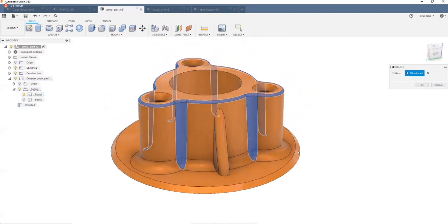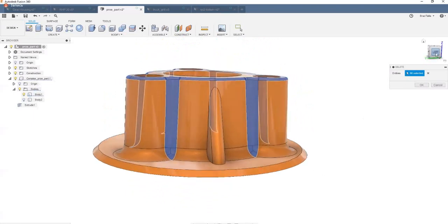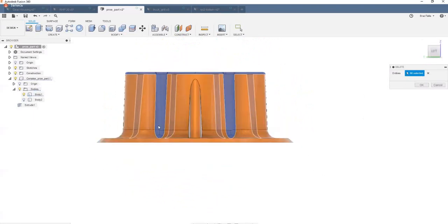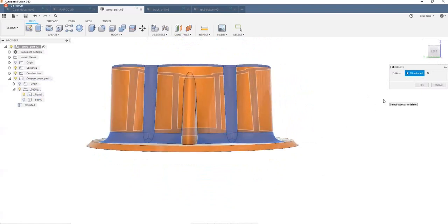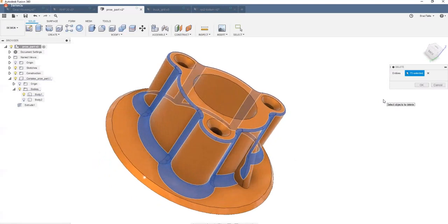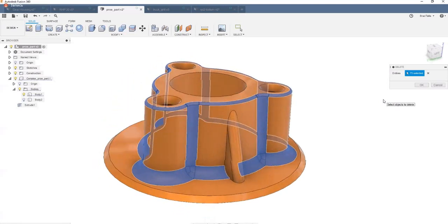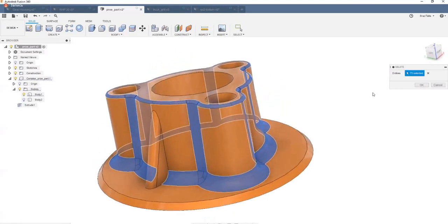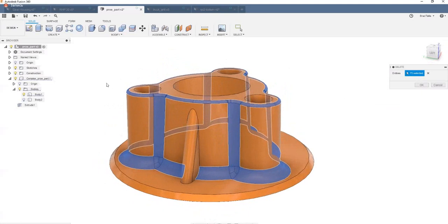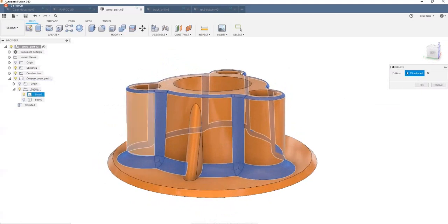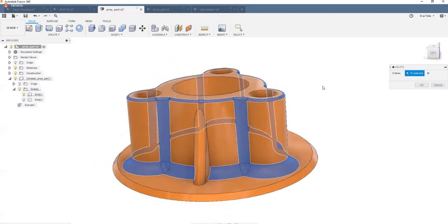And I probably should go ahead and select those big fillets on the bottom. So holding down my shift key, I'm just going to draw a box around something like that. And I've now selected all of those fillets or blends, 73 of them in basically 3 mouse clicks. Well, more than that, I'm sorry, in a few mouse clicks.